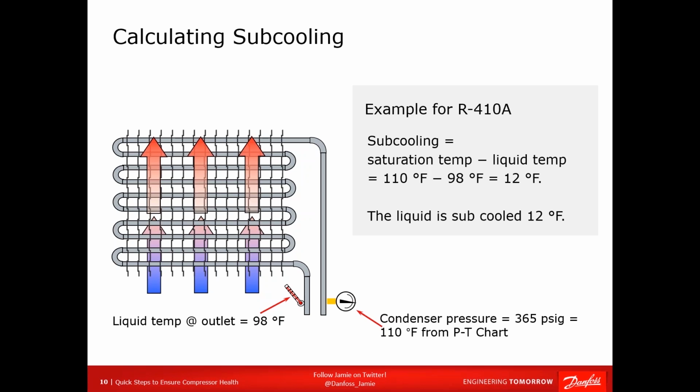subcooling. So just like with the evaporator, the longer that liquid hangs in the condenser before it leaves, the more subcooling you're going to end up having based on the temperature difference between the liquid or the refrigerant and the air.